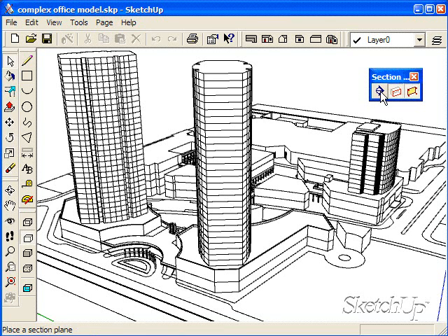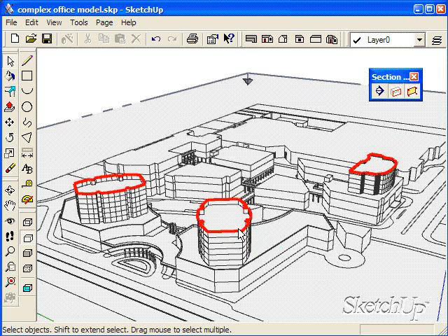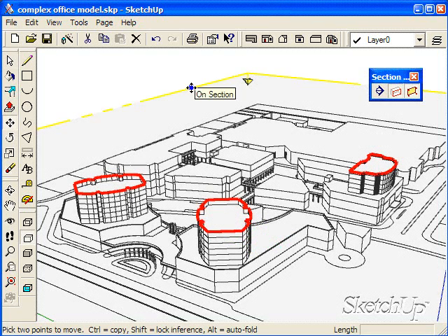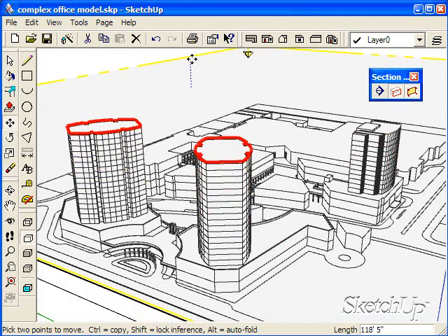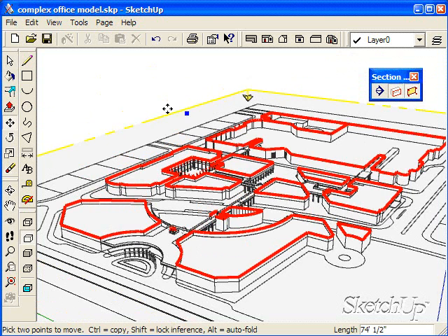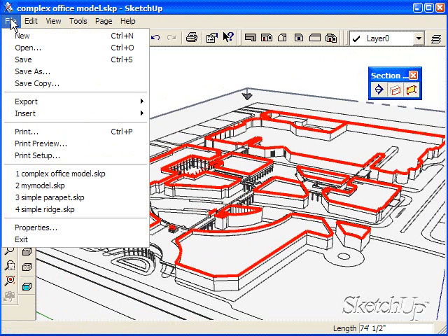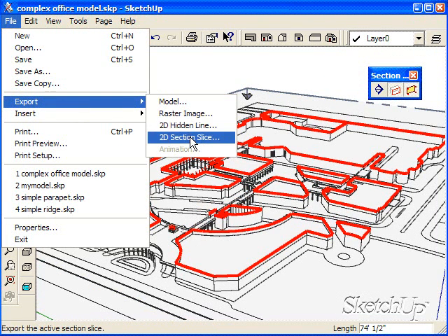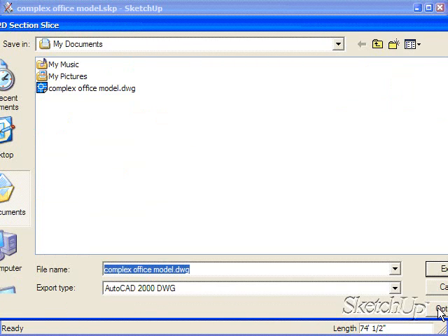Many SketchUp models showing large buildings or campus arrangements used for master planning do not lend themselves to simple geometry import, either by virtue of their modeling complexity or lack thereof. The best way to handle these models is to place a section plane in the model at each floor level, then export the 2D section slice, creating line work for the walls.